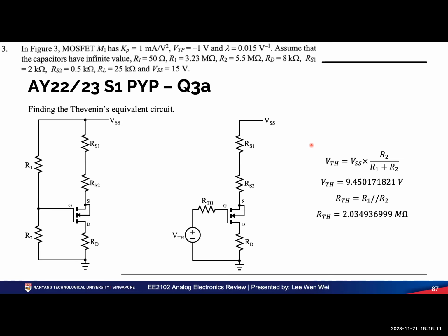So basically, you always need to find the voltage across the input and output. BJT is the same thing. You know BJT has base, collector, emitter. It's always between the collector and the emitter, VCE, or VEC, depending on NPN or PNP. In this case it's a MOSFET. There's a gate, source and drain. In this case, is it NMOS? This one is PMOS, yeah, PMOS.